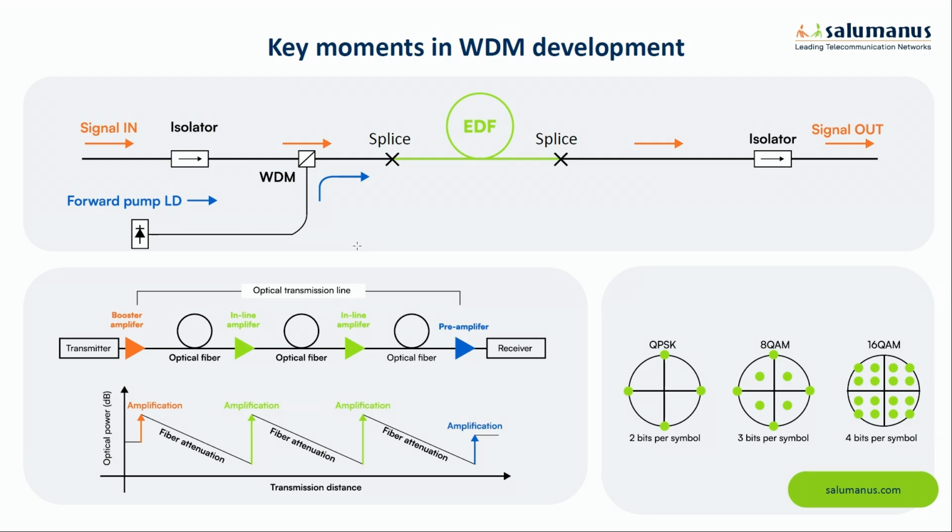Previously, when we wanted to send anything over a long distance, we always did optical to electrical and back to optical regeneration using something we today call a transponder. At that time it was basically a regenerator, because it only regenerated the amplitude. But now we have EDFA. With EDFA, we amplify the signal, the whole spectrum, not each channel separately.